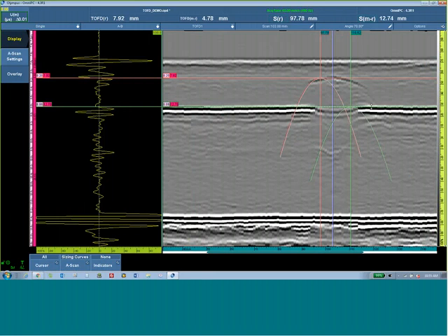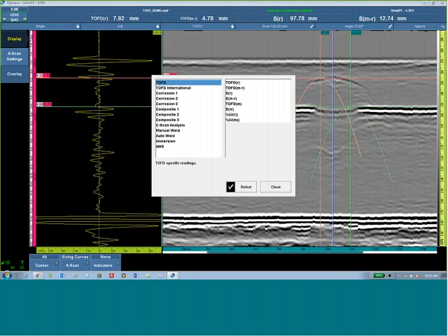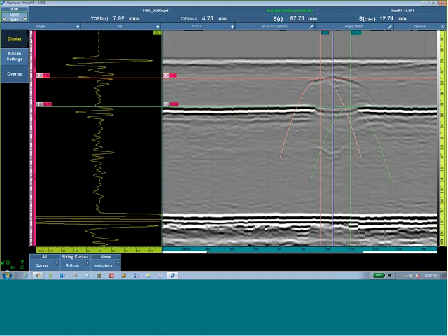So when we selected the TOFD in the setup wizard, it also defined the TOFD reading lists for the 4 groups of 2 for the relative readings. The TOFD indication you see here is an ID-connected crack breaking the back wall.